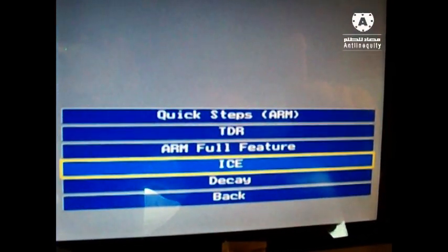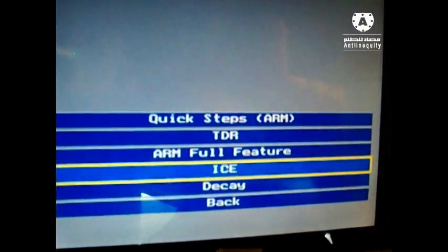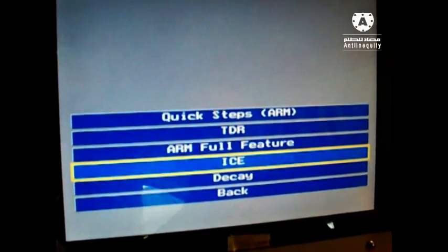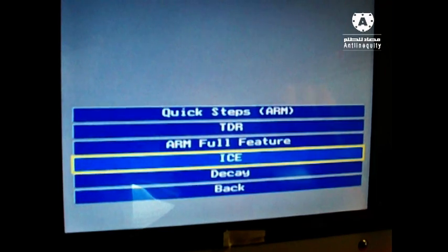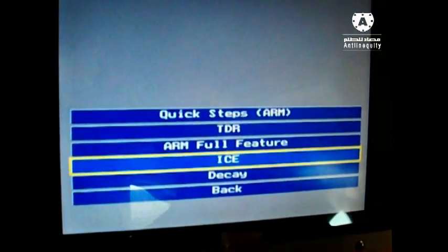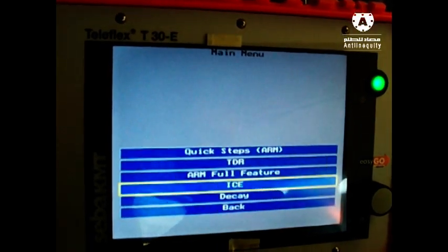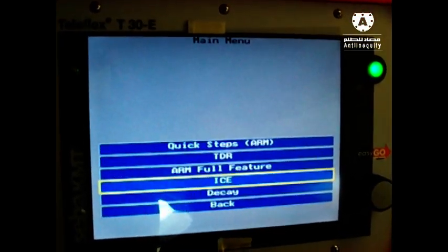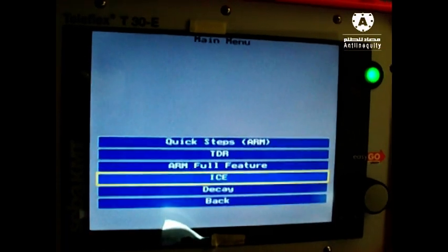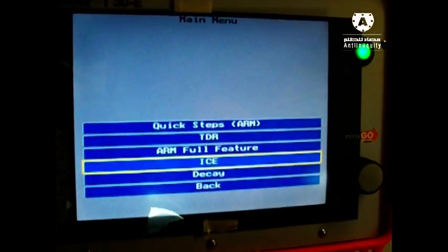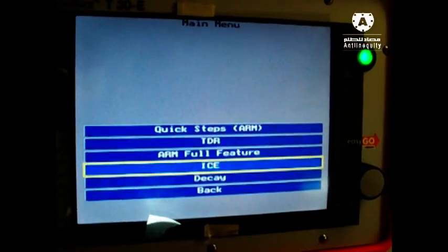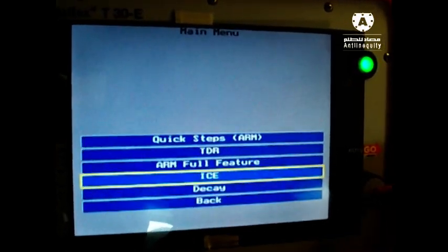When we set the cursors peak to peak for one complete wave, we get information about the distance from here to our failure. This is also a method we can use in every kind of high resistance fault, but not in a low resistance fault. Okay, so let's try it.